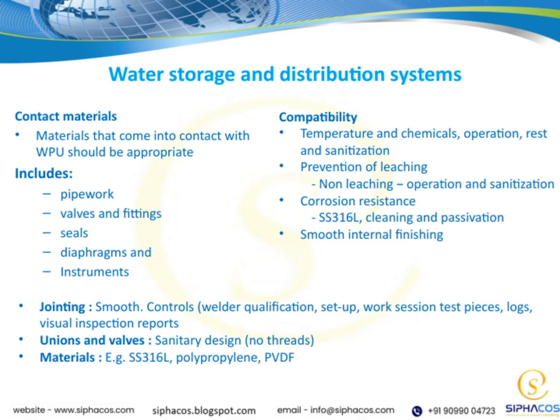Corrosion resistance is another major factor. For instance, SS316L is excellent because it withstands cleaning and passivation processes, which help maintain its integrity over time. Internal finishing should be smooth, especially for water storage and distribution systems, to prevent buildup and facilitate cleaning.